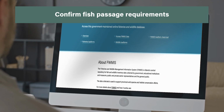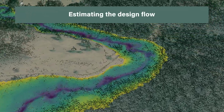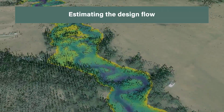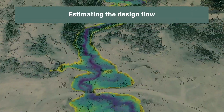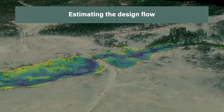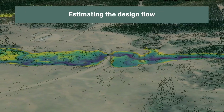Online tools are available to assist with these calculations. Estimate the design flow for flood peak within a defined time period, for example, a 1-in-100-year flood event, or based on regulatory requirements. There are regional flow monitoring stations and statistical methods to help with this estimation.